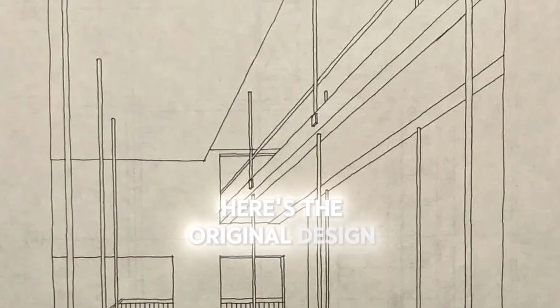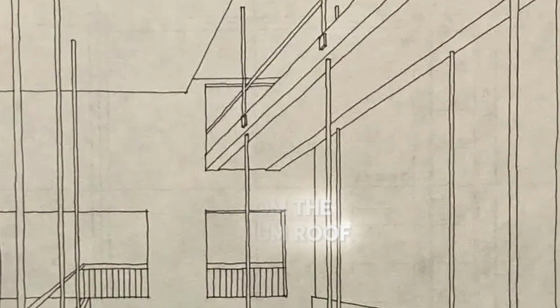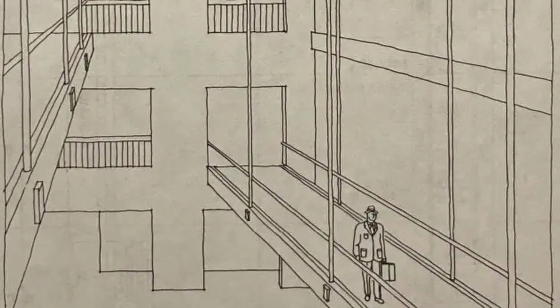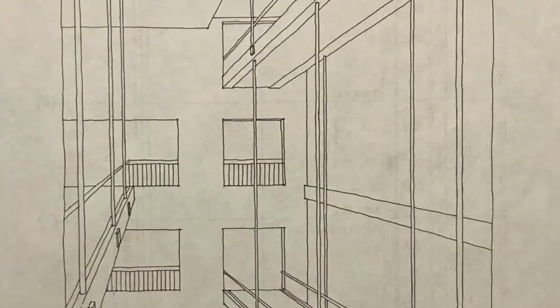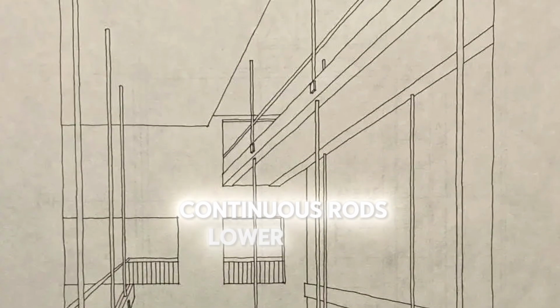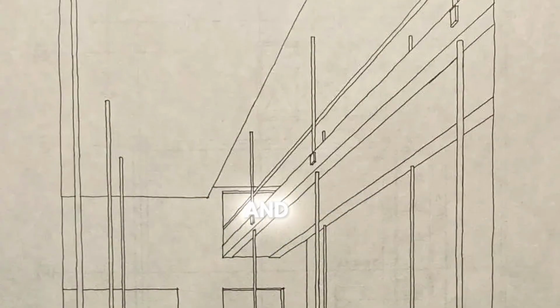Here's the original design. Long threaded steel rods run from the atrium roof all the way down past the fourth floor to the second. The fourth floor walkway hangs off those rods at one point. The second floor walkway hangs off the same continuous rods lower down. Each walkway's weight goes straight into the rod and up to the roof, independent parts.